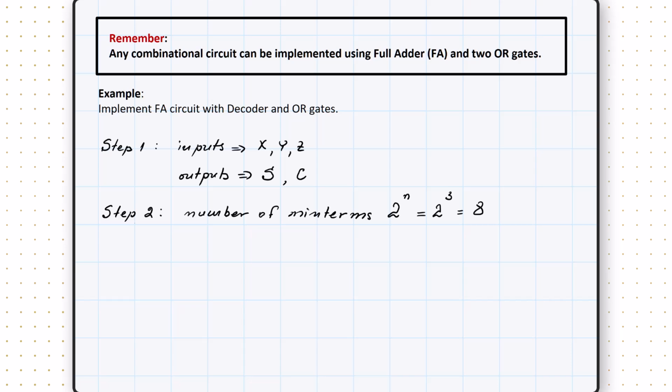Next step is related directly to organizing our diagram, so it's going to be creating a minterm table. The actual minterm table is going to consider the number of inputs, the number of outputs, and every single row will be related to a respective minterm. So let's go ahead and start creating our minterm table.